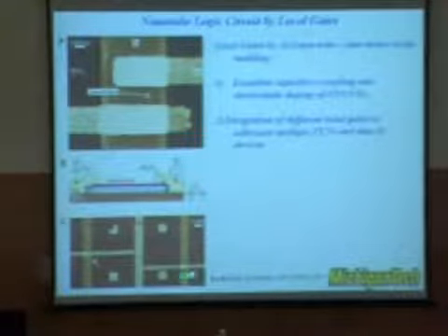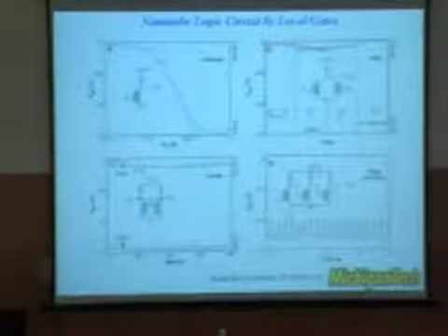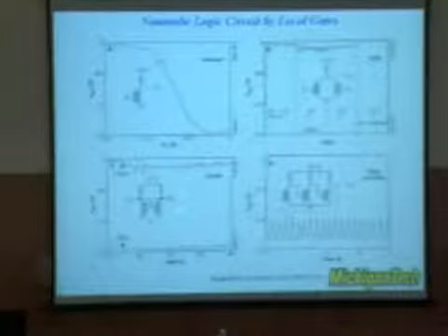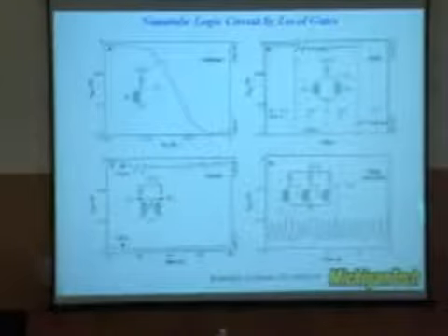So in this case, on one piece of the chip, you can have multiple nanotubes because all of them have their own gate. If you do so, you can form, by using one piece of the conduction channel, the inverter. You can use 2 pieces of them to form some logic gate or the memory device, and the oscillator as well. So what I would like to say is that many advancements have already been obtained by using single wall carbon nanotubes, right?